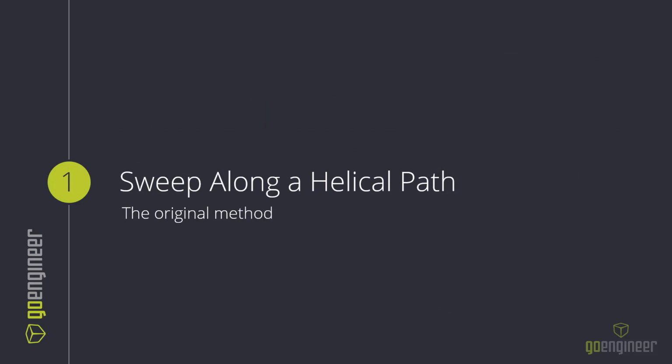Now the first method is sweeping along a helical path. This is the original method, so anybody that is familiar with SOLIDWORKS and has been using it since its inception, this is the method that they would use or they would have learned. What we're going to do is create a helical path, and then our profile is going to sweep along that path to create our